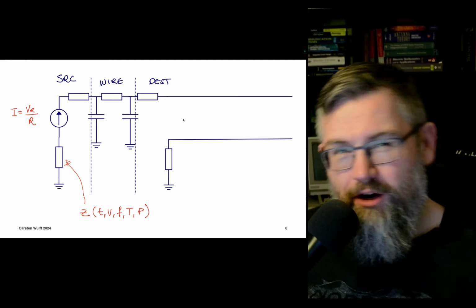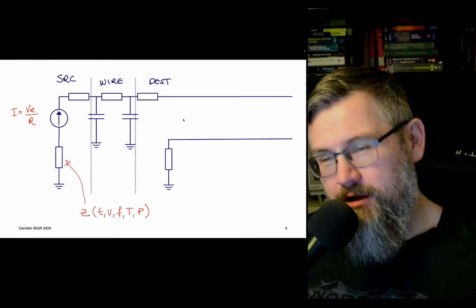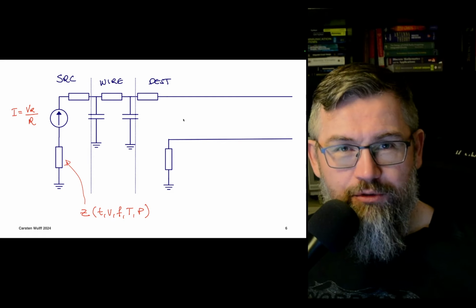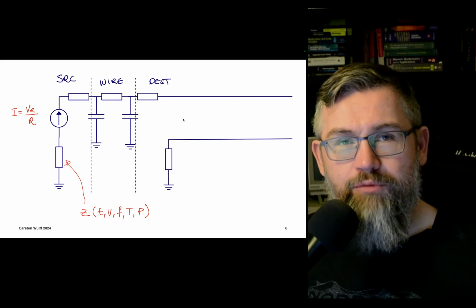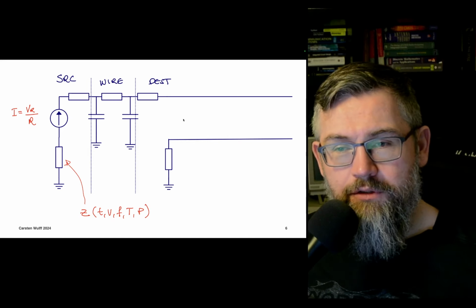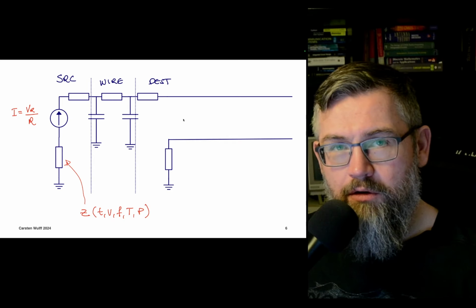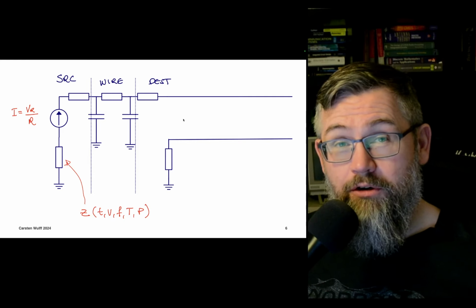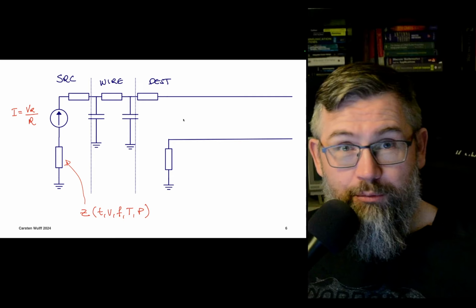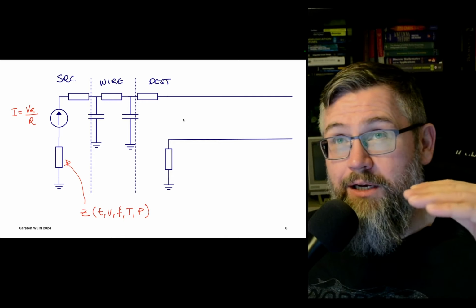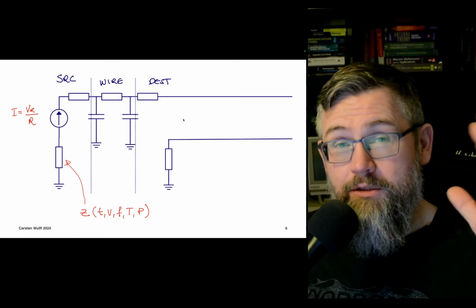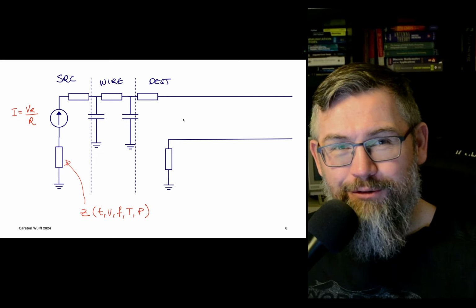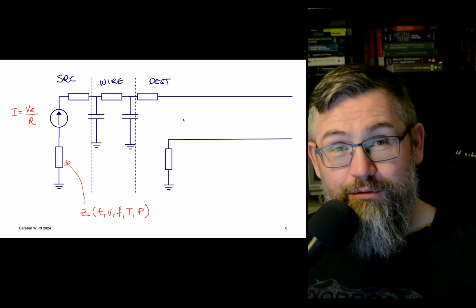However, we can't make resistors that precise. Usually, cross-die variation might be a few percent. So there are limits to how precise we can make voltage references or distribute voltage references with the method that I'm showing you right now. So if you want something ultra precise, like what you need for a lithium-ion battery charger where you have to terminate the voltage within 1% or something like that, otherwise things go wrong, then you cannot use currents as your distribution method. Then you have to use the voltage.